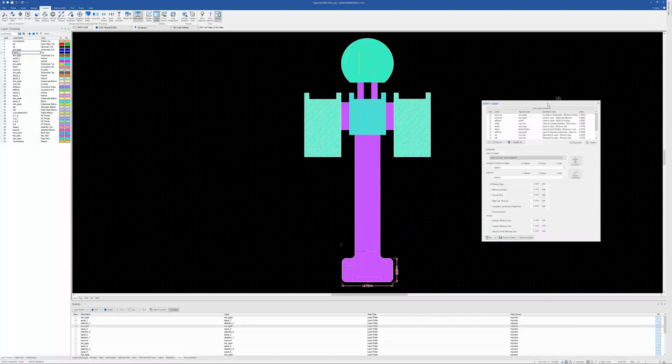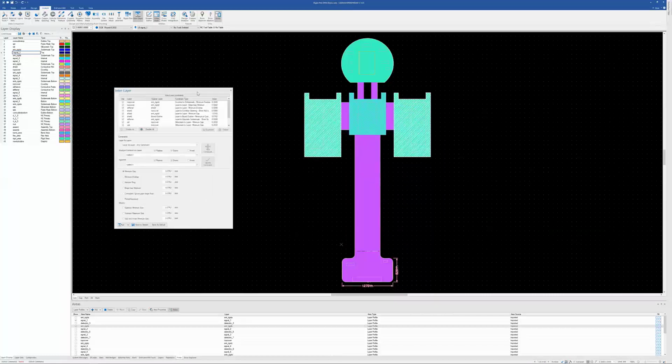And along with that, we added what we call interlayer checks. And we gave the user the ability to create their own. So we did this with rigid flex in mind. There's various types of checks that you can run: a gap, an overlap, an annular ring, the minimum to a gap, exposure or partial exposure, and then slivers of various types. These are the types of checks, but you decide how you want to run it.